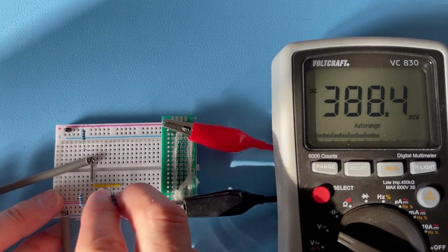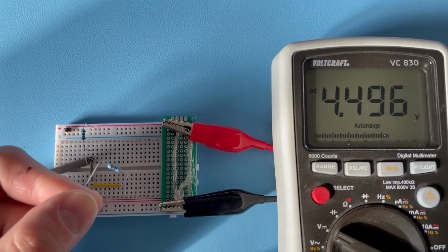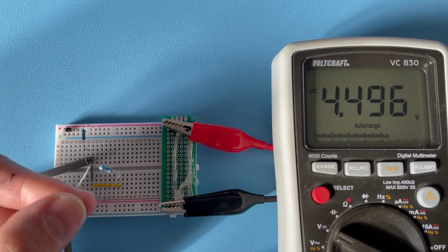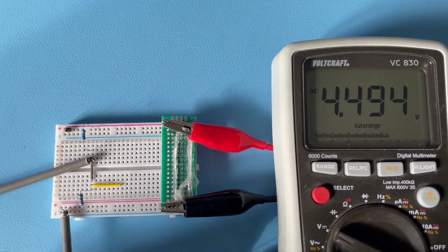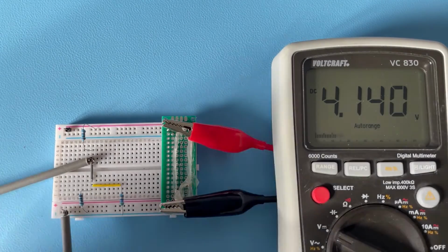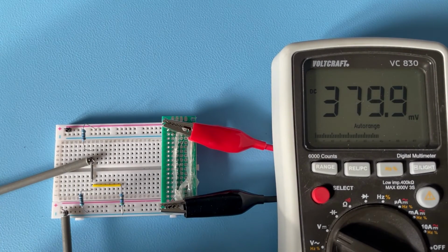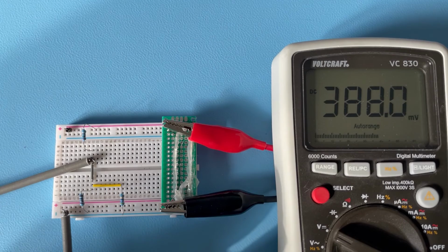And let's say this resistor would be my play car or my motor or something, and we would be happy, hey, there is 4.5 volts on this voltage divider, let's use that 4.5 volt, and you use it and zack, you fall down to 400 millivolt. And that's the problem of the voltage divider, you can't load it.